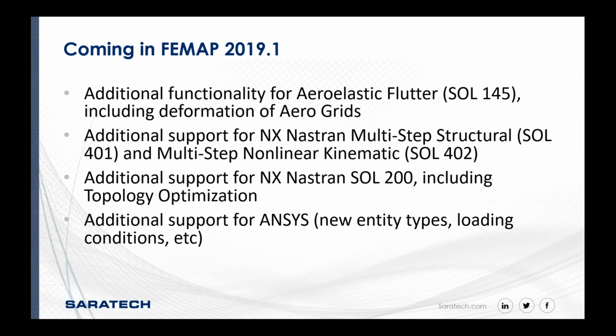We also have additional functionality coming for aeroelastic flutter. We're going to be able to now deform the aero grids, so you'll actually be able to correlate your aero panels with your structural model. In version 12, that was our first release that supports the two NX Nastran multi-step solutions, whether they be multi-step structural solution 401 or multi-step nonlinear kinematic